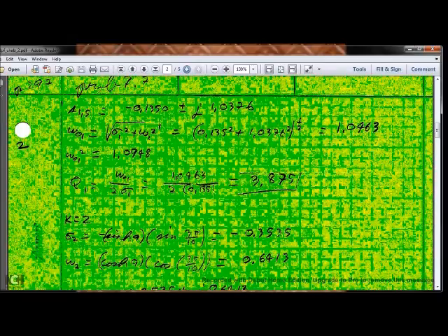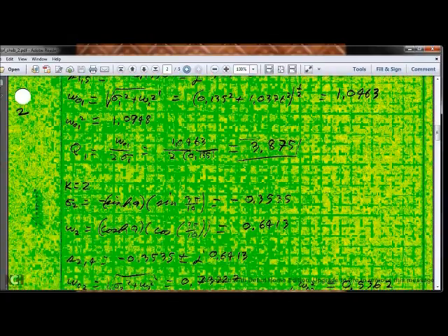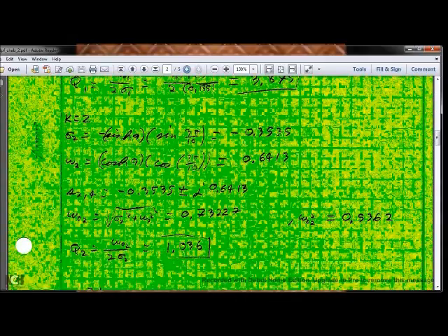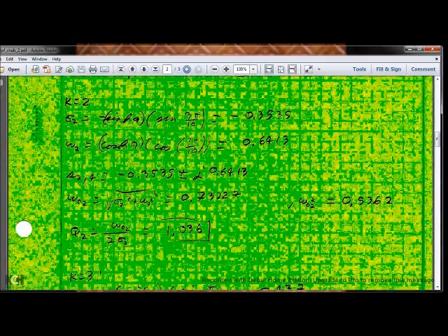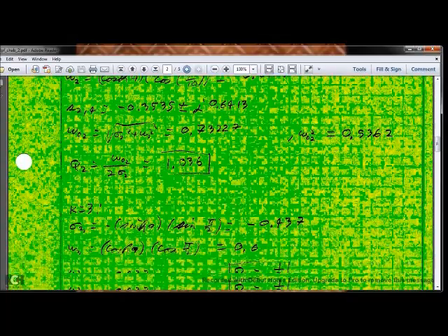And we have our natural frequency for one of our biquad sections. This is the first one on the right. We have that number. We calculate the quality factor, Q1, 3.875. This is the largest magnitude quality factor that we have, so it will be last in the cascade. The second pair of poles in the denominator we have here, and we have our natural frequency and quality factor for the second biquad section.